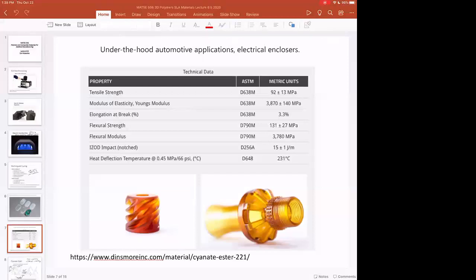All of those printers basically use the same idea to do this liquid to solid photopolymerization of these acrylates and methacrylates and a couple other different types of monomers. And then it's really up to the resin formulation, the resin recipe, the post-curing, all of the other stuff that goes on after 3D printing that allows you to obtain useful parts that can be used in applications.